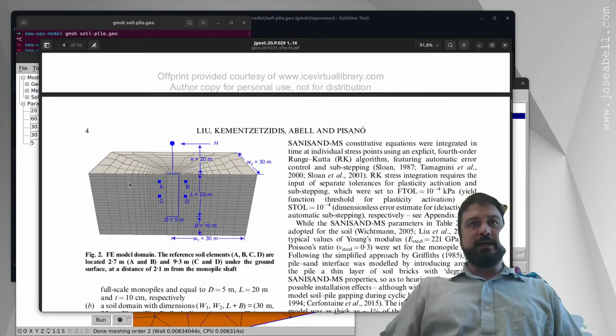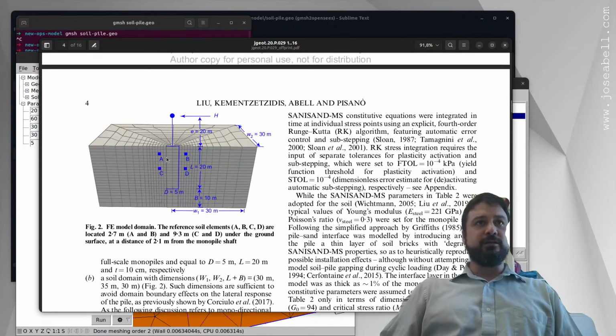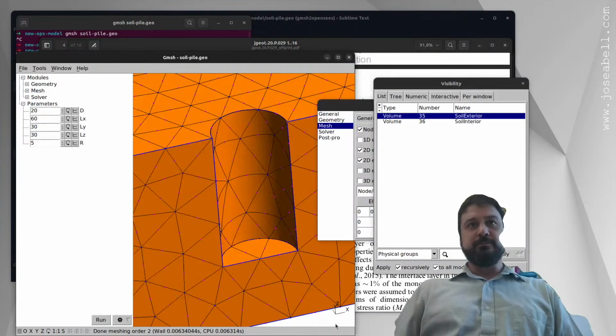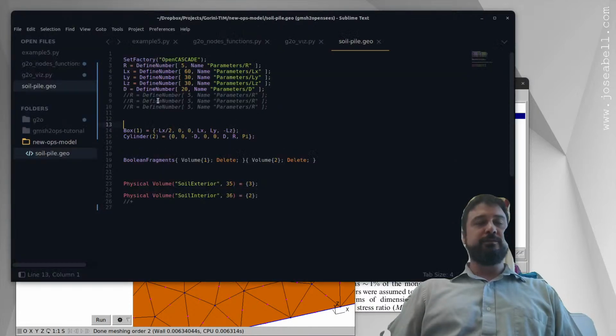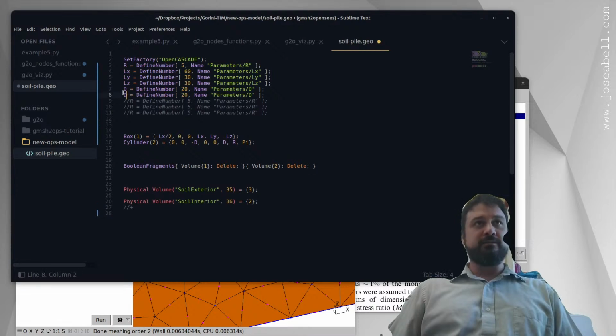in this paper, what I had is the shells were modeled using actually the bricks, the same bricks, but disposed very thin, in a thin layer. I could do that here too with high order elements. But it's simpler to work with shells. I don't know, I could set up both models. It should be easy. Like let's have a thickness here. Thickness of the steel. We could do that.